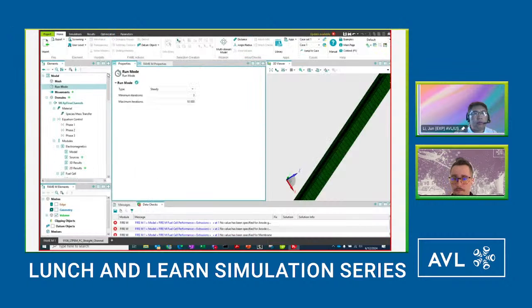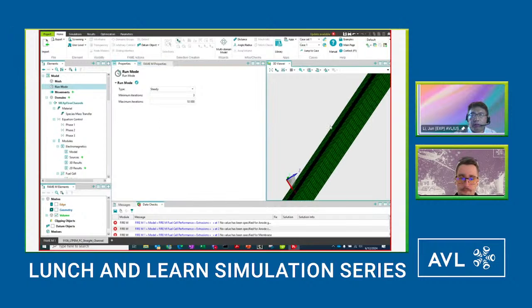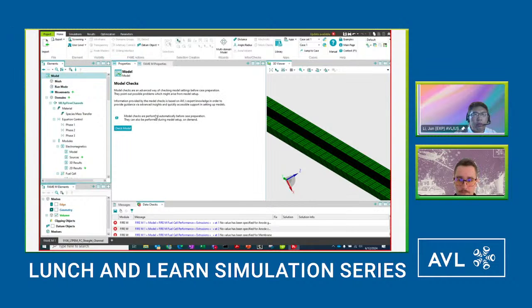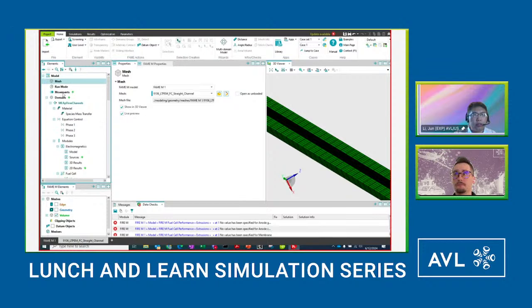I'm just going to walk you through a little bit of our FireM setup. This is the straight channel simple case. In this setting, first of all, we have a model check, which will automatically check the model setting. If there's any problem, you will see a warning in the data check section. This is the mesh part, and then this is a simple steady state simulation.